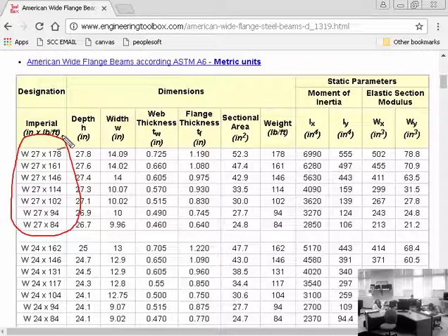About 30 feet. About 30 feet ordering is about the length, because that reflects what kind of truck they can bring it on. They can bring it on bigger for sure, but when you order sticks of material, you're probably going to be looking at about 30 feet max length in terms of decent pricing. You start going over that, you get into custom stuff. And most people try to figure out what sizes do they need to order so they can get the most bang for the buck and have the least amount of leftover.